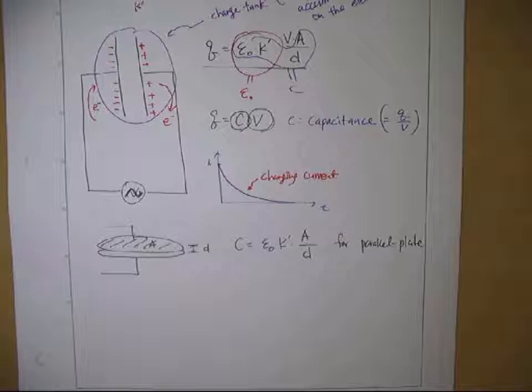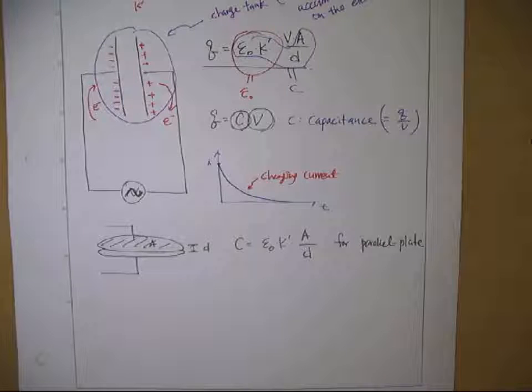So let's think about the capacitor first. It takes time for charge to accumulate. Once the charge is fully saturated, you don't have any current going in and out, right? For the same DC voltage. What if you apply an alternating voltage? If you change the polarity of the voltage, then the electrons have to move to the other side to charge it, right?